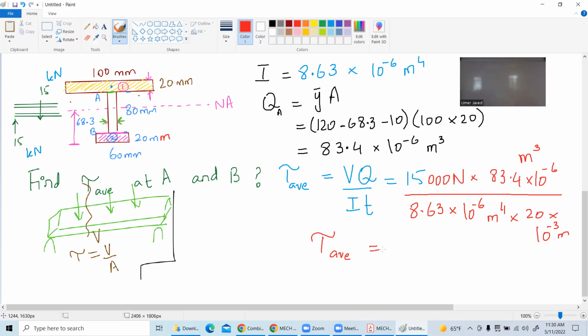Boom. When you say area, you think like this. You see this layer thickness of contact. If you take it to the third dimension, that will be the area we are talking about for those fibers. So the contact area will be this green little chunk, the area of interest for shear. I've glued these two together over that area, and there is a force acting here and also a force acting here, which is delta H. So it's similar to V divided by area, where the area will be the contact. Delta H will not be V. You can say synonymous if you want to use the word, but they are different.